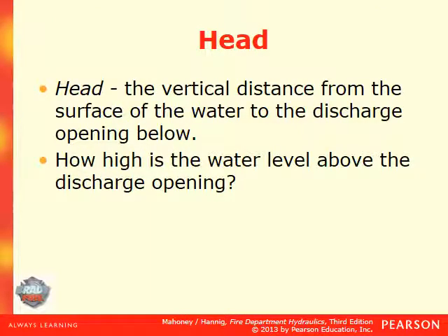Now, the pressure at that base is known as the head pressure, which is the vertical distance from the surface of the water to the discharge or the opening below. How high is the water level above the discharge opening?